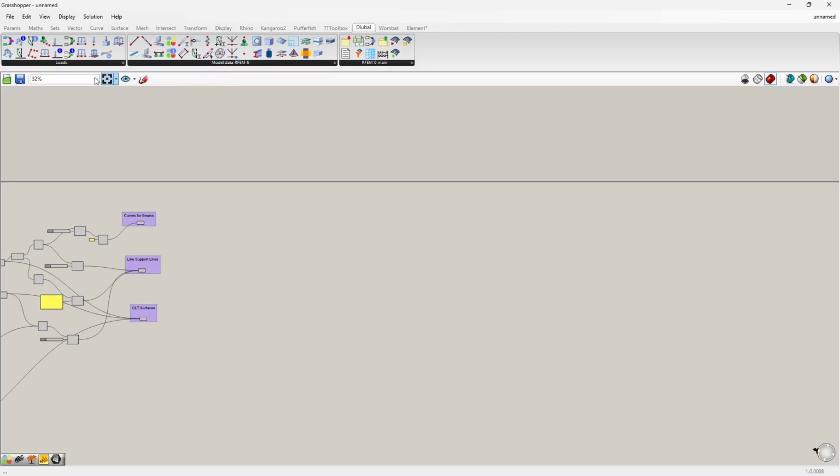We have another group which is called loads. In here you have components to create load cases, load combinations, but also the loads, nodal loads, line loads, member loads, surface loads, but also imperfections, in case you want to assign them as well. And the last group contains general components, for example the export component, the import component, a component that allows you to run the calculation of RFEM 6 via Grasshopper, or other components. For example, as I said, I use in an internal version the global mesh setting component.